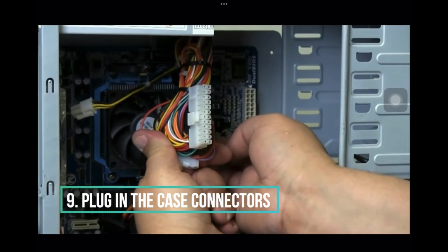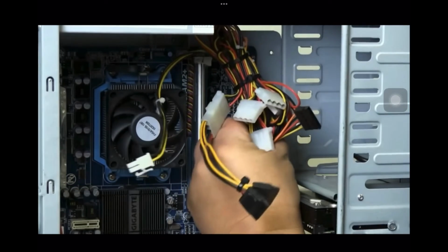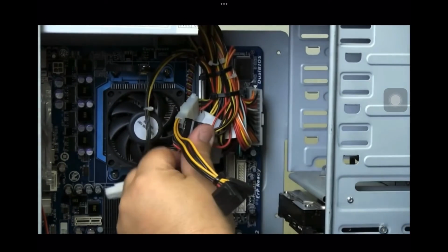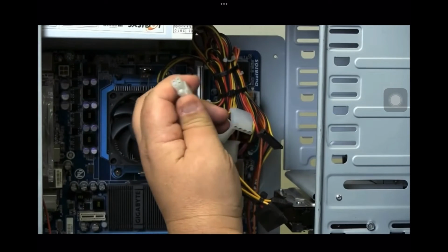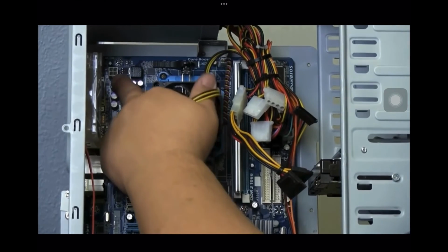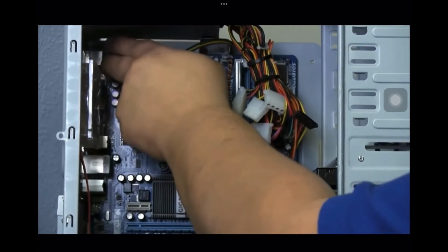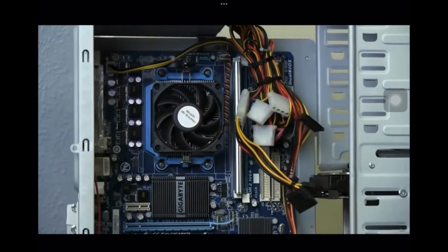Step 9 is plug in the case connector. These tend to be located together on the motherboard near the front of the case. The order in which these are connected will depend on which is easiest. Make sure that you connect the USB port, the power and reset switches, the LED power and hard drive light, and the audio cable. Your motherboard documentation will show you where on your motherboard these connectors attach. There is typically only one way that this connector can attach to the motherboard.